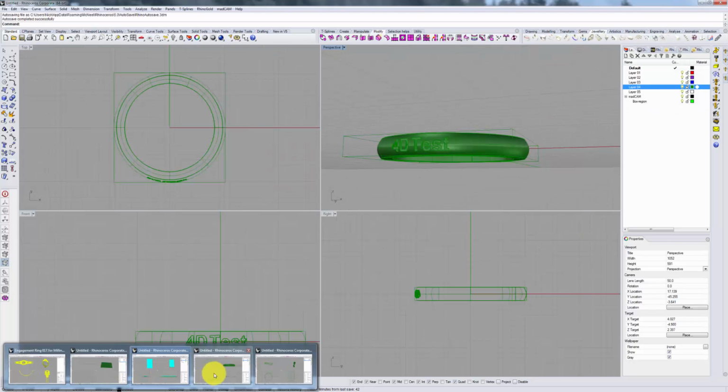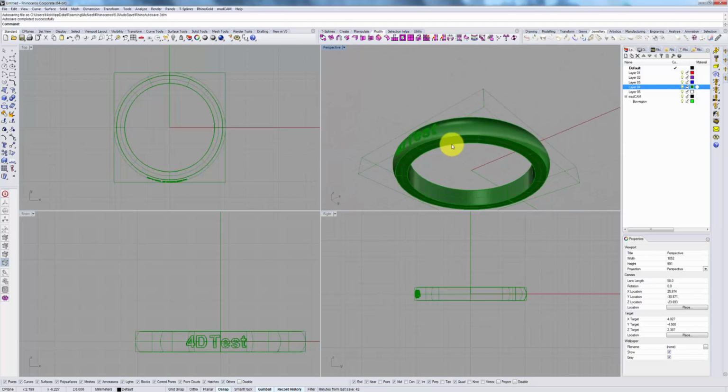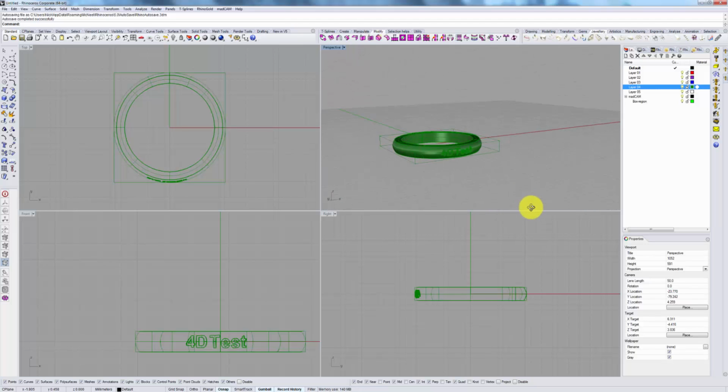Now, moving along, let's do a 4-axis cutting. So 4-axis basically refers to rotary style cutting, whereas in 3D style cutting you engage 3 axes, the X, the Y, and then the Z to go up and down. The 4th axis strategy allows you to rotate the piece as it's performing all of those other 3 movements.